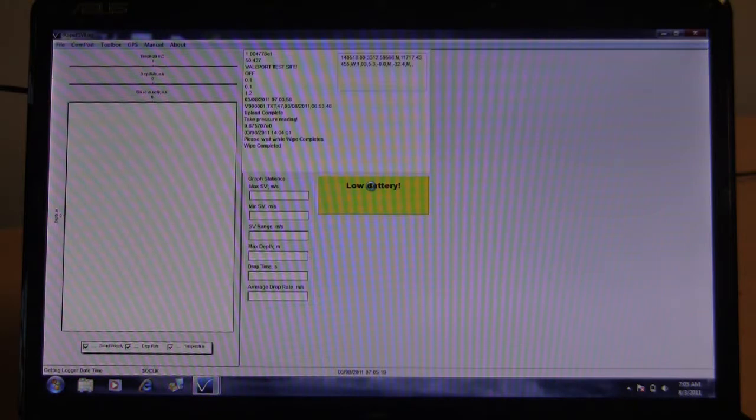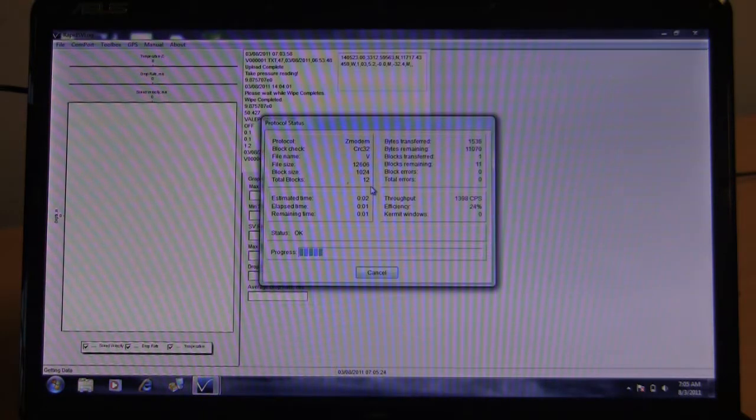The probe's been taken out of the water now, so after the 1 minute time's up, the software is going to automatically interrogate the probe and take the profile off, which will include the GPS position at the time the probe entered the water. You can see on the display here on the left, obviously it was just in a bucket of water, so there's no valid data here, but it does show the graphical display of the sound velocity and the drop rate. And for this probe, if you had a temperature sensor enabled, we would have temperature also.